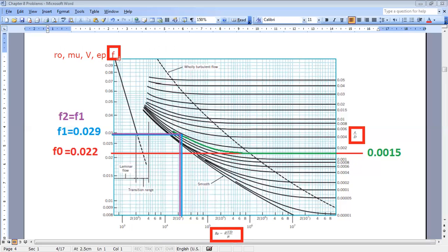And experimentally, what they did, they varied. For example, you can fix, let's say, 2 parameters and vary the other. And at the end, when doing several experiments, you can come up with a curve, with several curves. Okay, these curves, when you put them together, represent what we call the Moody chart.